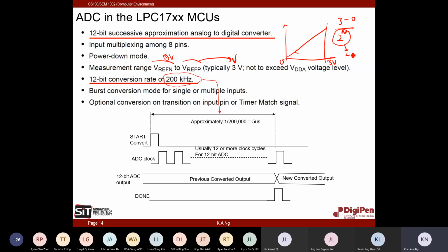All right. Of course, like I mentioned, if you want to do high resolution acquisition for audio or for something special, don't take this number wholesale. It may actually be less because the ADCs may have errors. Don't use up the full range. You may actually get errors, and it can be quite fatal for certain cases, especially if you do servo motor control.